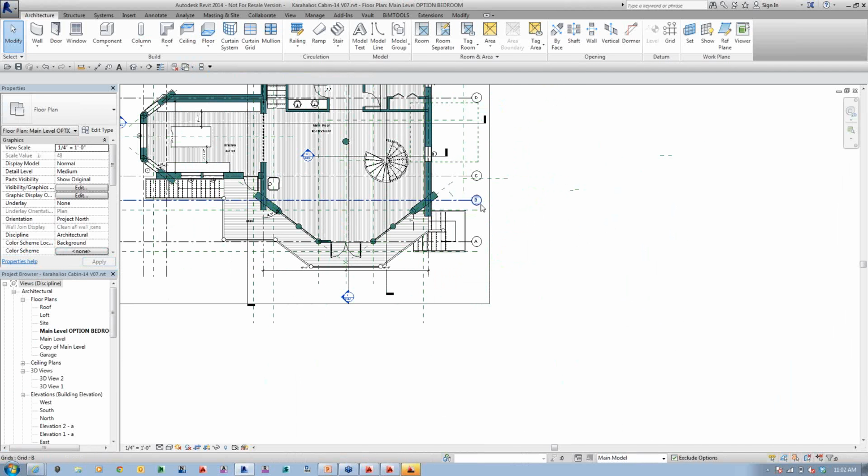We've got a comment from Kevin. For trusses, I have been using in-place structural framing, simple sweeps, extrusions, void and solid. In this environment, the join command copes them. So, there's another little tip for you, perhaps.